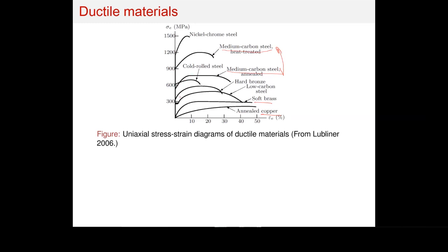And if you look into the behavior, you'll see that there are no straight lines in there. I mean, we try to identify a straight line right at the beginning of this curve. For steel, we have something distinguishable, but for different types of alloys, you don't have that. And this elastic range would expand beyond the linear part. So this is why I said nonlinear doesn't mean plastic.